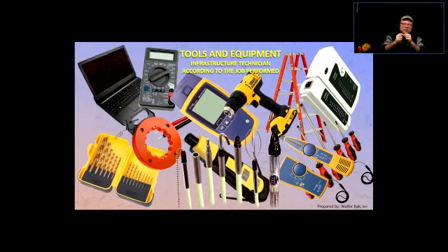If the tone doesn't disappear, there could be one or two options. One, it could be that you didn't get the right pair. It's just a bleed through from another pair, so it could be the one beside it, right? Or if one of the wires from that pair is broken, then when you shorted that, the signal still doesn't disappear. That means the circuit is not complete, the circuit is not closed. You still can hear that tone. And if that's the pair, then the pair is not good because you don't have a pair. You just have one wire and the other one is broken. Okay? So it's for tracing wires that are not labeled.